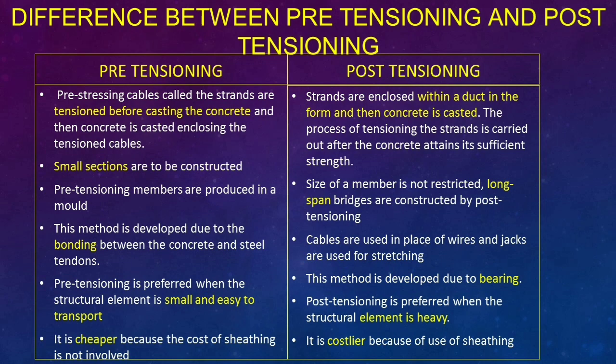Pre-tensioning is preferred for small sections, whereas post-tensioning is preferred for long span structural elements. Pre-tensioning is developed due to the bonding between concrete and steel, whereas post-tensioning is developed due to bearing.